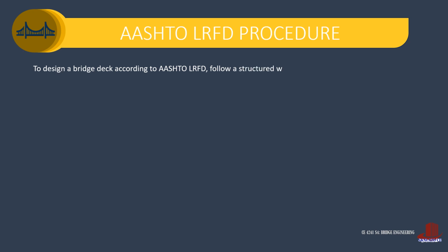AASHTO has the LRFD procedure in the design of the deck. It starts from the identification of the bridge geometry to the calculation of the shears and moments, then the design of the reinforcements down until the limit state verification. Let's make a quick rundown of the steps.